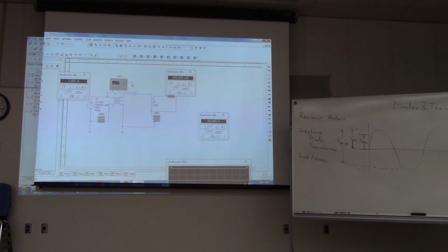So that'll probably be less than 1 ohm, but you figure out what that is and you write that down. That's the first measurement you're going to make, and you write that in your book. Then you attach the leads to the two ends of the coil, and you measure the resistance again and write down that value. That's basically the resistance of the leads as well as the resistance of the coil.